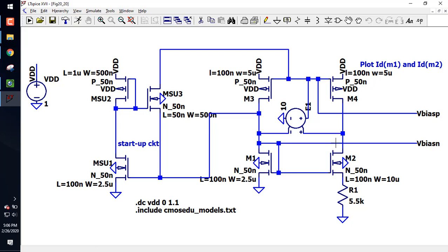So I determined this is a higher impedance than this. I note that when I move this up or down, I'm turning on and off these 2 transistors. These 2 transistors provide a current through each side that's the same. So I want negative feedback. I want, as I adjust this signal here, for the one that's got the negative feedback to move more than the one with the positive feedback. Because then, it's just like this.